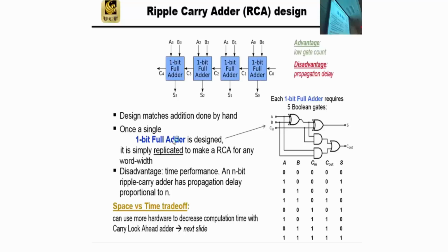A lot, because first you had to generate C4. So first you did 50, the sum was 100 picoseconds. The carry was even more, because we had 1 gate delay. I'm not wasting your time, this is the next question, we're actually calculating gate delay. So this is 50 to get to this output, because this box takes 50 picoseconds, that's what gate delay means. And then you have to put it into this box, another 50, and then 150. And then you have to do another case of that, another case of that, another case of that.